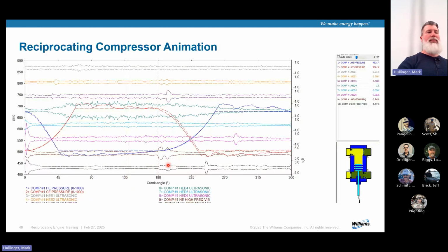Okay, here's an animation of the compressors right here. They're double acting, which means you get work or action on each side of the piston. Okay. So you've got expansion right here, suction valve opens. And then it recompresses. Recompression takes it up to discharge temperature, discharge valves open, and repeats the process.